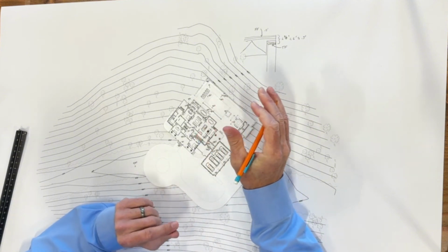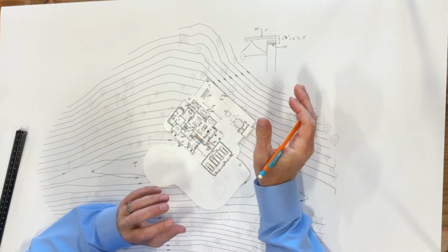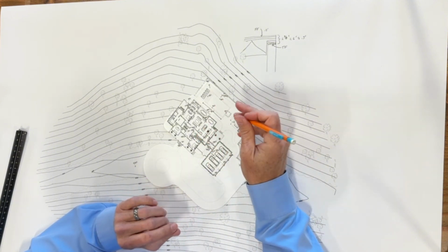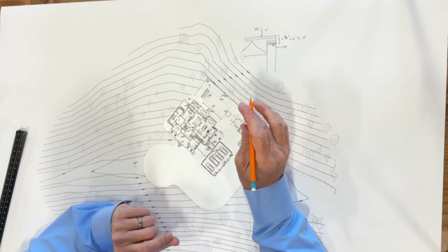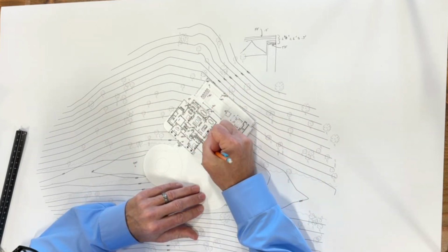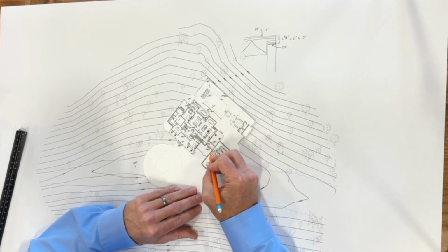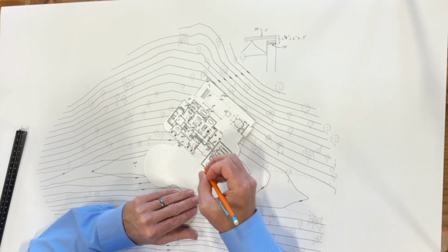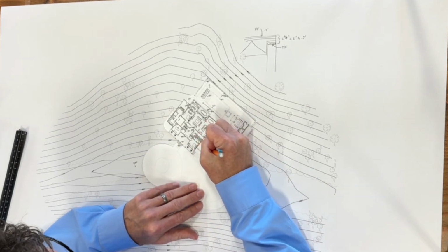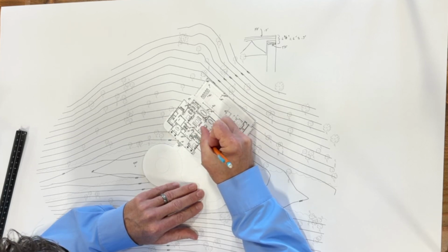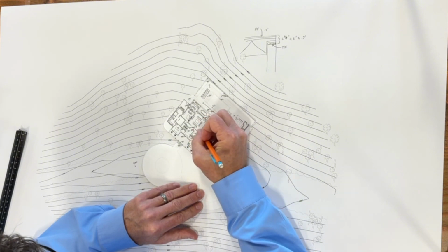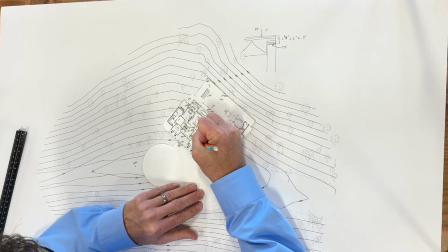And you always have to think about any of these site plans, like where does a drop of water go? Like you have to get a drop of water out from every spot. And the toughest spots are these courtyards because the water has to come out and then go around. So that's a 941.5. That's as you come down that step. That means this is probably similar to here, 941.5.